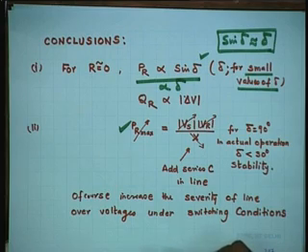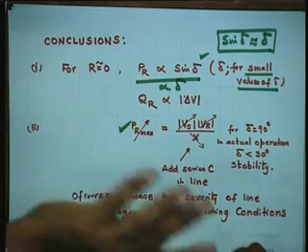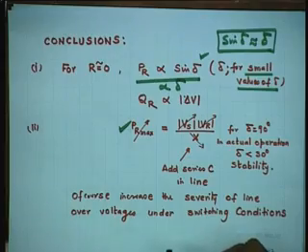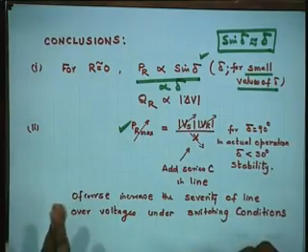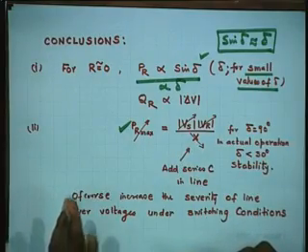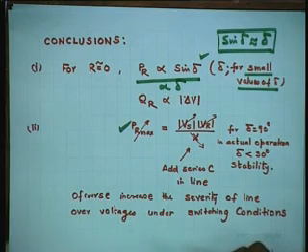How do you reduce X when the transmission line is already built? Before building, yes, bundle conductors, aluminum, copper, ACSR, whatever you can do. But having purchased a car, Alto or whatever, you can only play with that car. You can't say I need a Mercedes. You are stuck with that car. So, once the line is built, the only manipulation possible is with X. That is all built. You can add lines, of course, but that is a one-time solution.